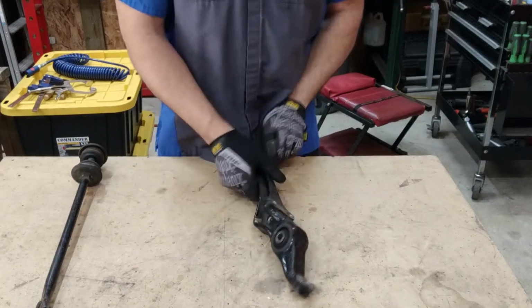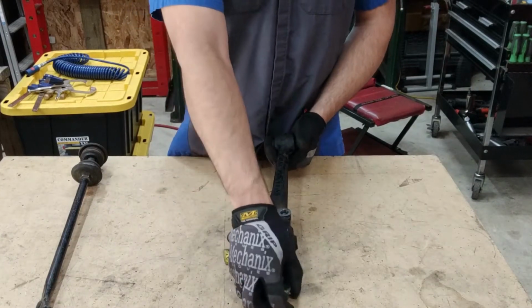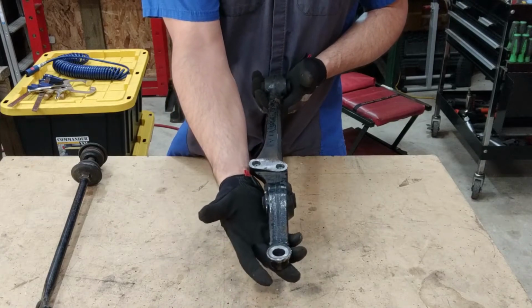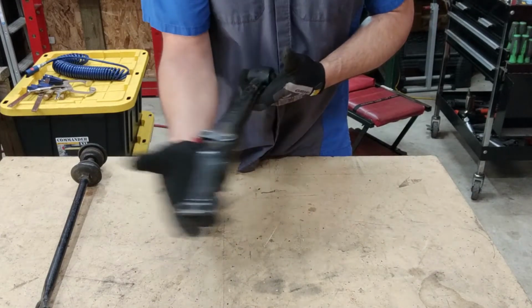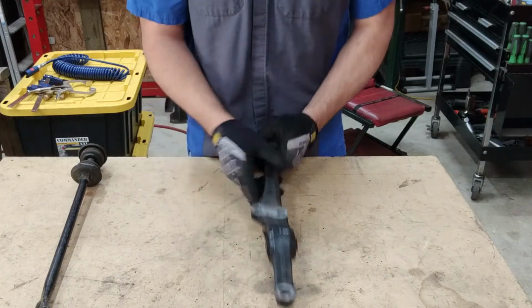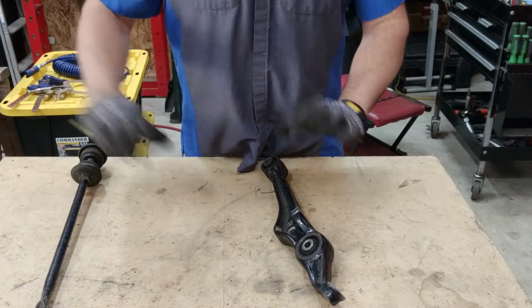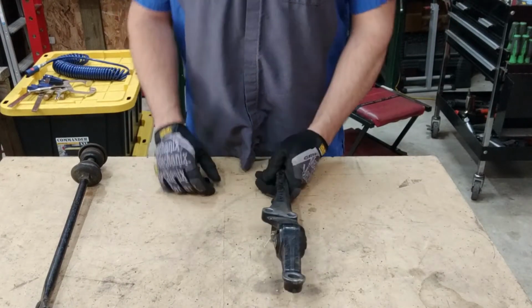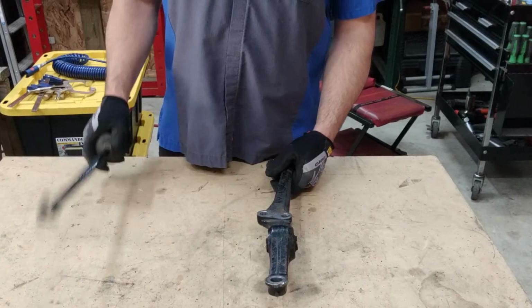In order for this component to resist the forces acting from the tire back to the control arm, it needs to be controlled fore and aft. So we're not supposed to be getting this movement out of this control arm, because then our wheel and tire would be moving back and forth in the fender and hitting other components. Not going to be safe, not going to be practical.